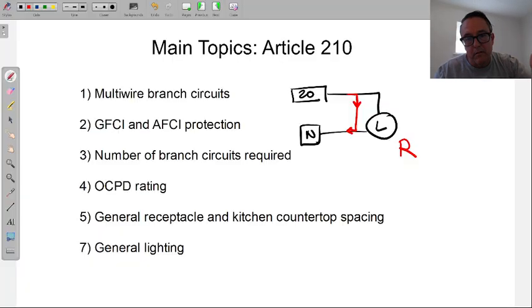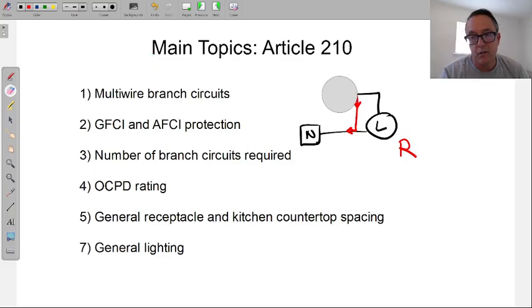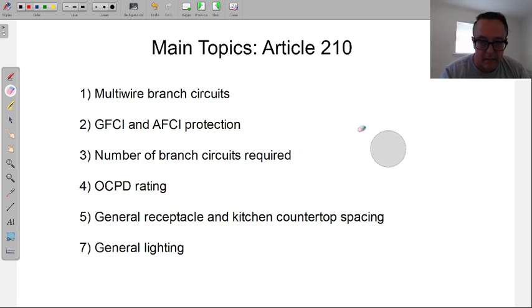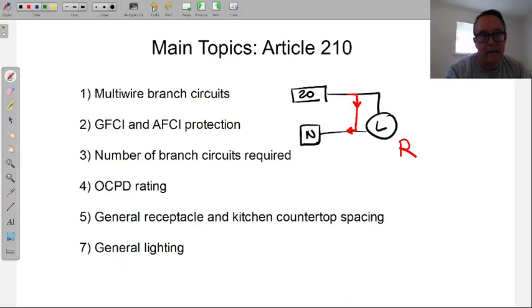The ground fault is different. The ground fault has no circuit issue because the ground and the hot do not make a circuit. They do not complete a circuit. The ground is only there to protect. Actually, let me bring that back and use it. I have my ground also in the panel, and that ground also goes to the load.